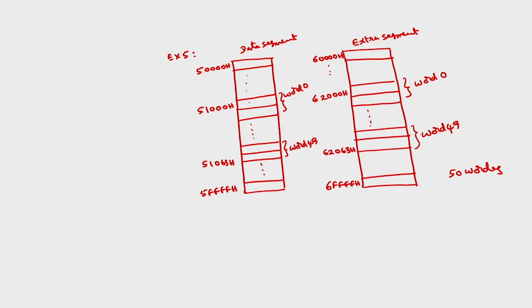For example, if you have 3E3F, and this is also 3E3F, after the first comparison itself, you have to stop. Otherwise, if the 16-bit words are different, then you have to go for the next comparison. So we have to stop at a point where both the words match, that is one condition, and the second condition is if the end of the array is reached.